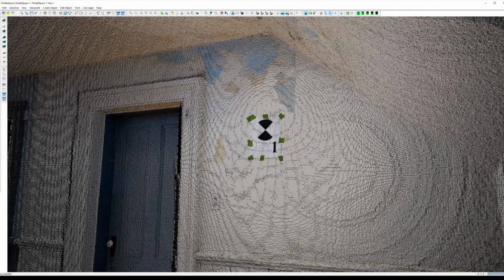You might say, yeah, maybe we can put a point right there at the center of that target. This target is about 1.5 meters away from the scanner or from the camera, which makes it easy. You might have a point right at the center. However, if we have targets that are further from the camera, the resolution will decrease, which means you have fewer points on the surface of the target, so the probability of having a point right at the center of the target is pretty minimal.